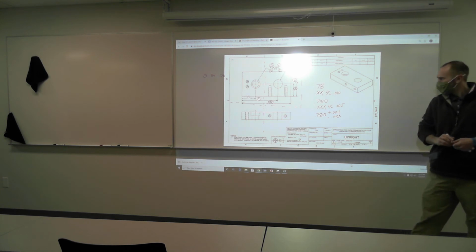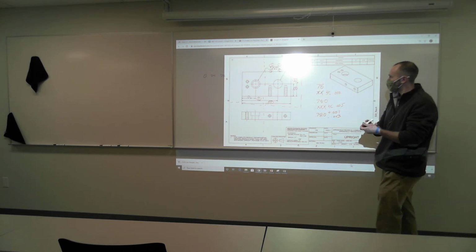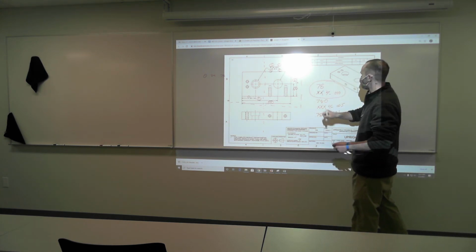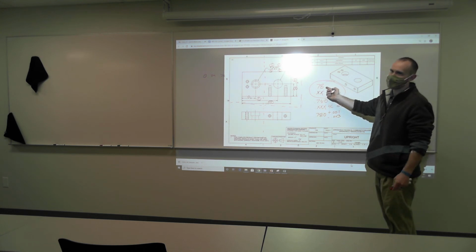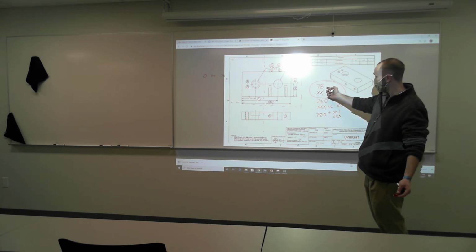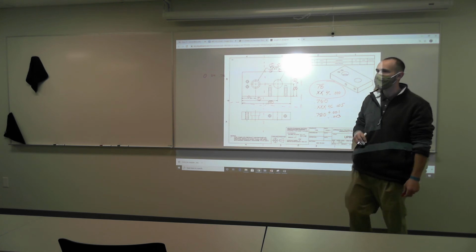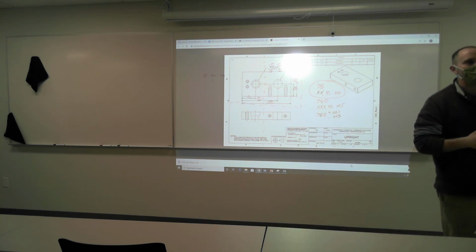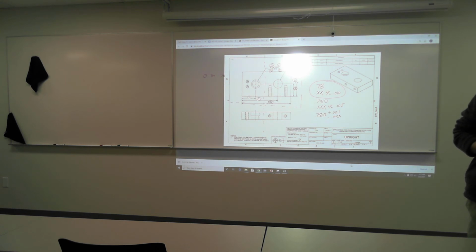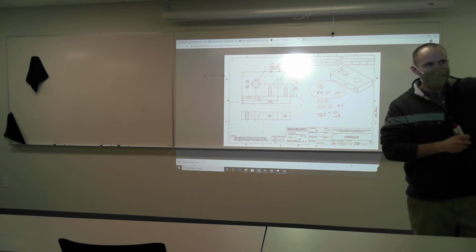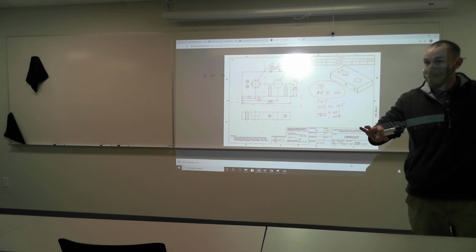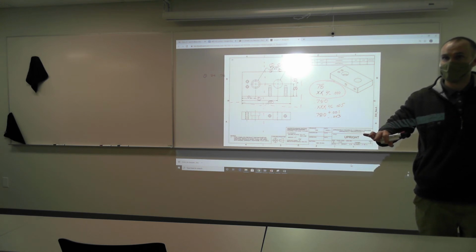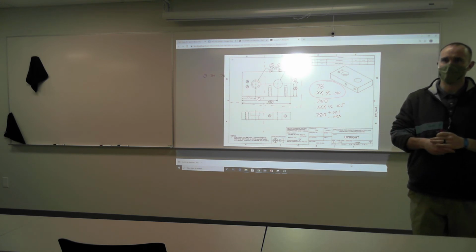So bearing in mind that we do have this case right here, this 0.78, a machinist would still say that is 780 thousandths. But when you look at the print, you say, yeah, 2-place decimal, I got plus or minus 10. So our high limit is 790, our low limit 770. What type of gauge do you think we could use to do a manual verification? If the CMM gives us wacky results, which they will from time to time, what gauge are we going to use to verify?